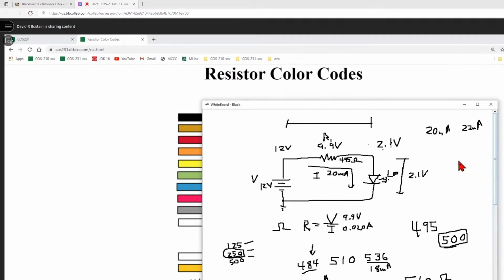Scott, do you have a question? Yeah, in the real world, when we're choosing the power rating, if we're kind of bumping up against these fractional ratings here, would you want to bump up? Like if we calculated a wattage of like 245. Yeah. It's kind of a soft science of figuring out what you need to do there. But if you got a rating that was something like 235, I would start getting antsy about that getting awfully close to 250. If you told me it was 220, I wouldn't be worried.